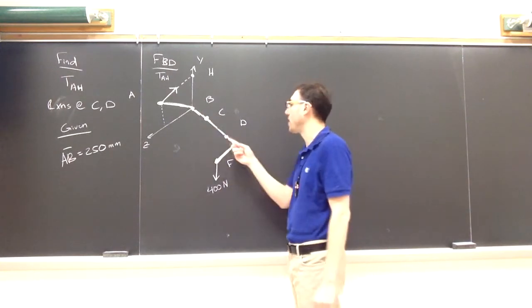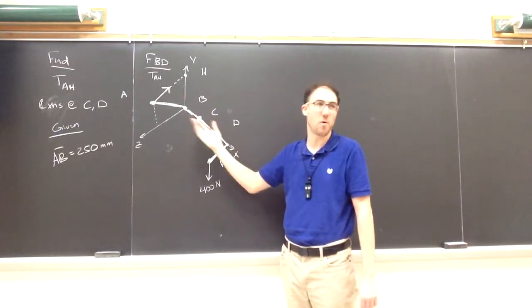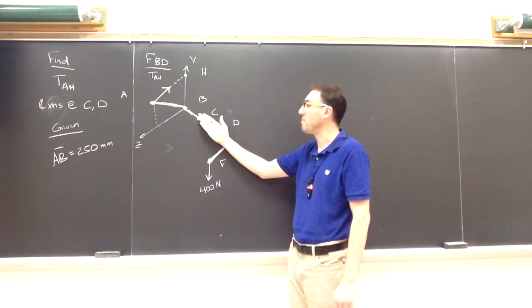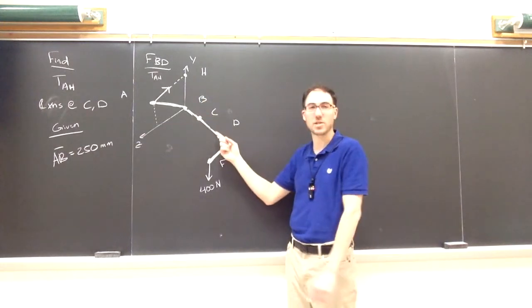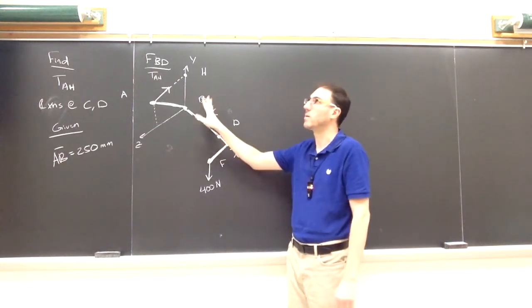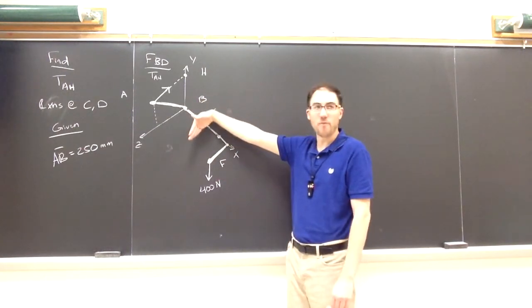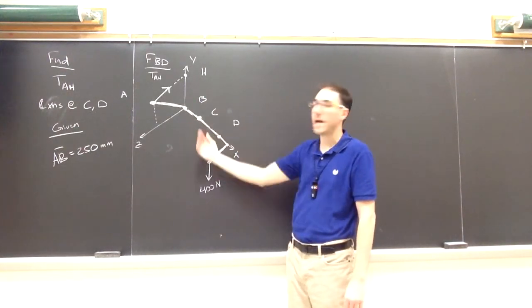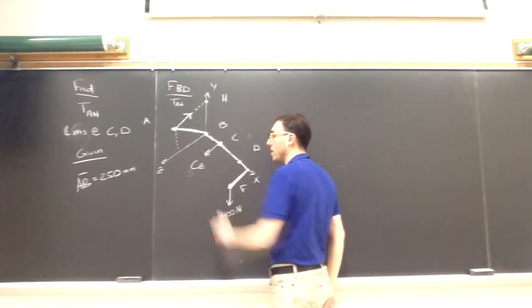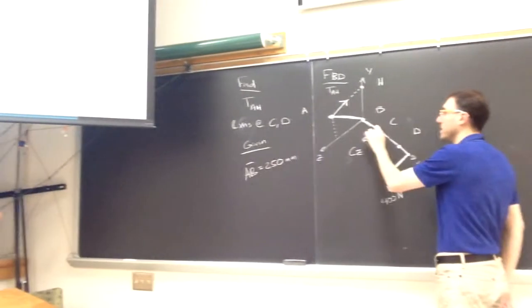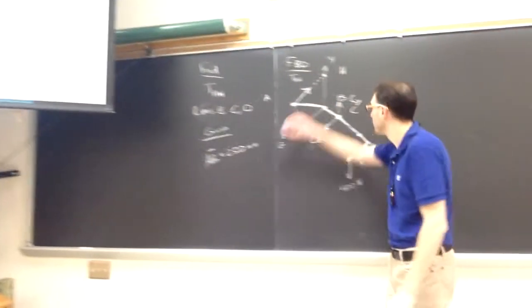So in this case, if the shaft is along the X direction, both bearings, whether it's a journal or a thrust bearing, will prevent it from moving in the YZ plane, since that's the plane normal to the X direction. So at C, whether it's a thrust or a journal, there'll be a component of force in the Z and a component in the Y. I'll call that CZ, assuming positive in the Z direction, and CY, assuming positive in the Y.